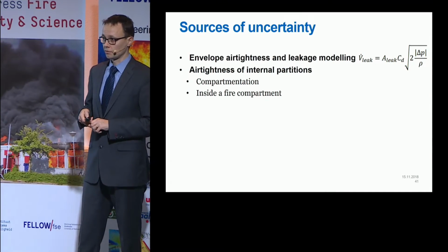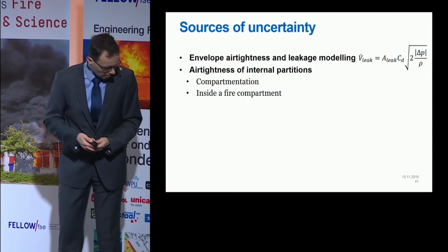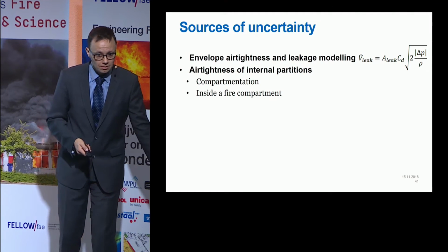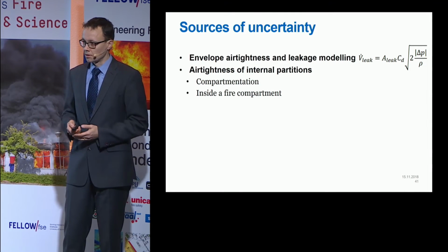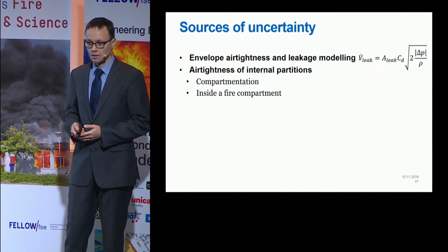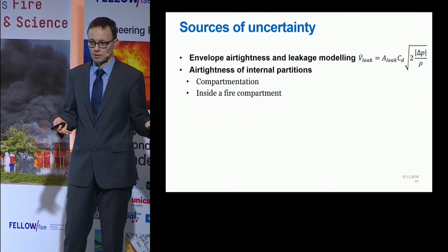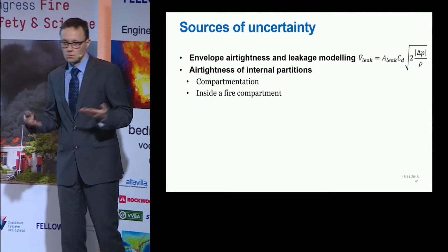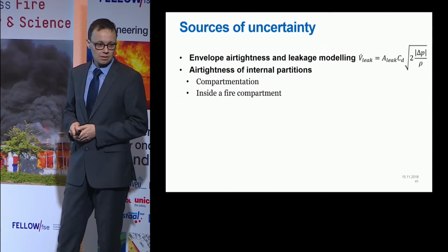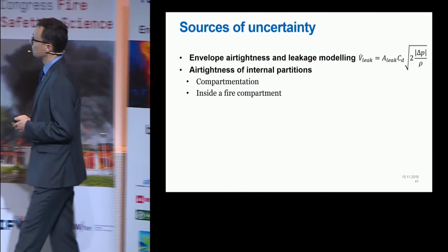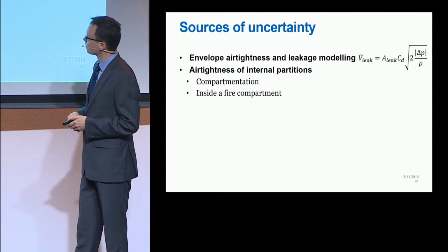Sometimes I have heard Finnish firemen tell that they saw smoke spread from the electrical plugs. Okay, that happens. But it's under the walls, yeah. Usually they have been quite minor leakages. You notice it happens, but it doesn't have any safety significance, really. It's not going to challenge the life safety. But, yeah, it's going to affect the pressure calculations.